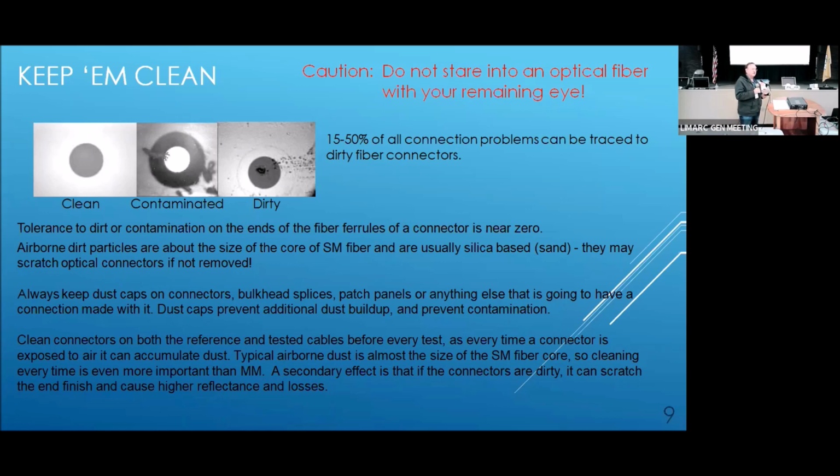One final question. At one time, with the undersea cables going across the Atlantic, I believe they had problems with sharks chewing on the cables. Has that been resolved, and how did they resolve it? Okay. They found out that the sharks chewing on the undersea cable was a result of the power frequency that they used. To go undersea, you can go 40 kilometers, but then you need a repeater. So an undersea cable typically has quite a few repeaters along the way, and those are fed by relatively high voltage lines, a couple of kilovolts. Copper lines are embedded in there to power the repeating equipment along the way.